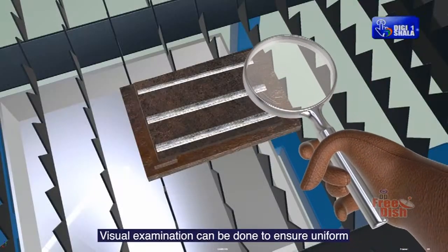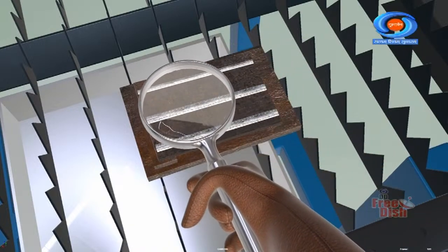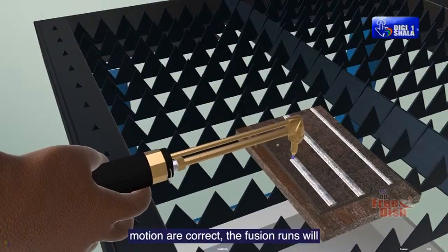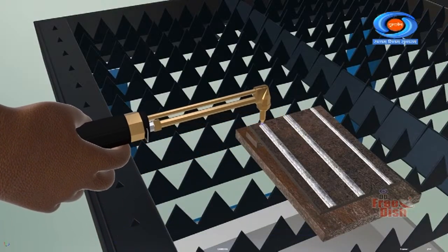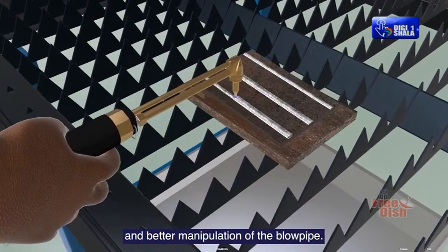Visual examination can be done to ensure uniform width, ripples and proper depth of fusion penetration. If the speed of travel and blowpipe motion are correct, the fusion runs will appear with uniform width and even ripples. Repeat the above to achieve uniform fusion and better manipulation of the blowpipe.